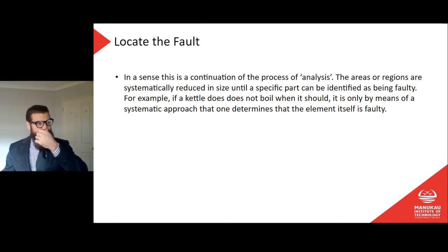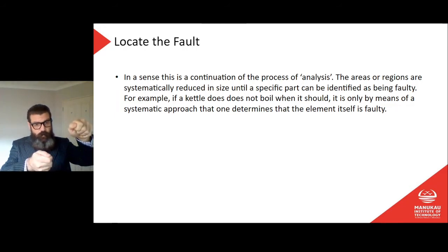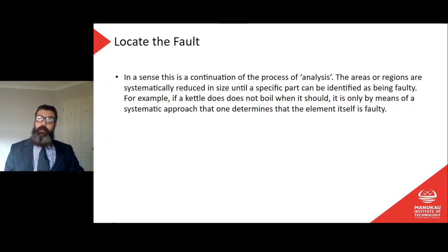So now I've got to break it down. What's my next step going to be? Well, the next step would be, okay, I need to figure out which circuit has that earth fault on it. So then I would have to turn off every circuit breaker and then do the same test but on the output side of the circuit breaker. Earth bar to output of circuit breaker 1. Test there. Is there an earth fault? No, that's a high reading in megohms. Okay, that one's good. Next one, next one, next one, next one, until I find the circuit. Once I've disconnected all those circuits from each other, then that one circuit will show up as being faulty and the rest of them should be safe.